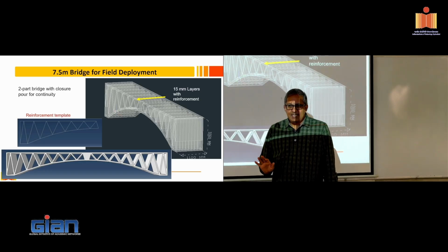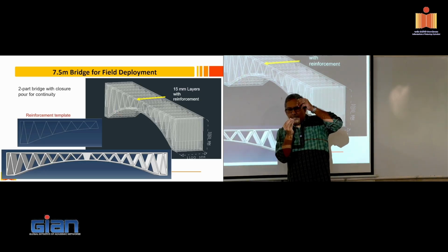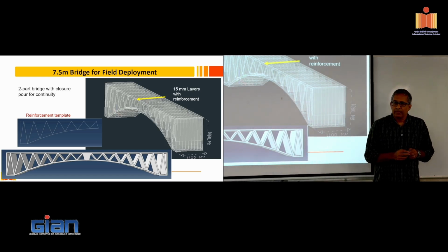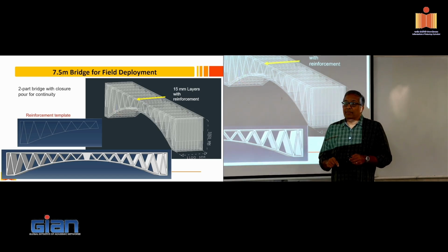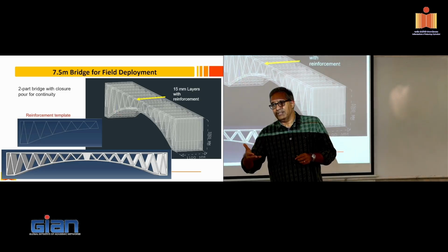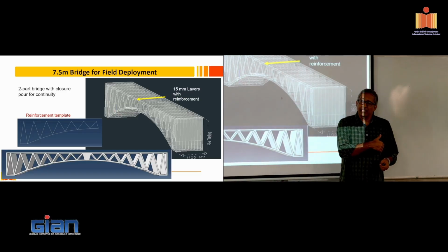And it was not intended for providing major structural response, but to take care of that little bit of tension that is in those diagonal tie elements. Yes, those are actually addressed at the material scale. So basically, if I don't have a proper mix where I'm not able to address that, you'll see cracks as you're printing. So that is usually addressed in the material mix design itself.